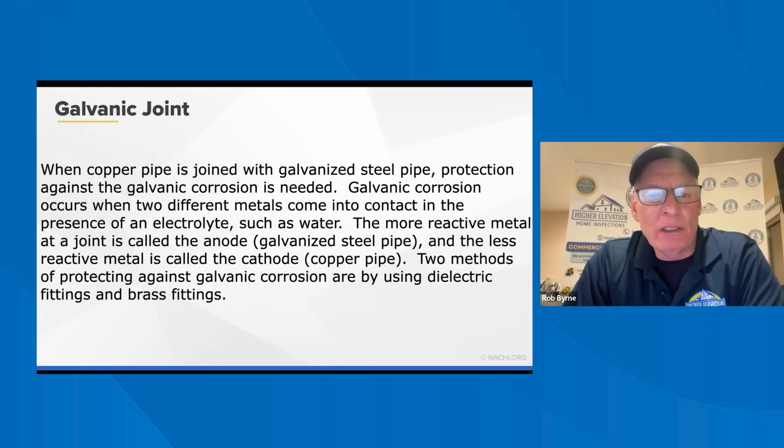Okay, this is exactly what we were talking about. This is a great illustration of a ball valve, a globe valve, and a gate valve. So you can see the difference. If you could see it on the slide, the ball valve, when you turn it, it's that stainless steel ball that literally just closes up the water flowing across. With the gate valve, you're turning it and you're pushing that gate down.